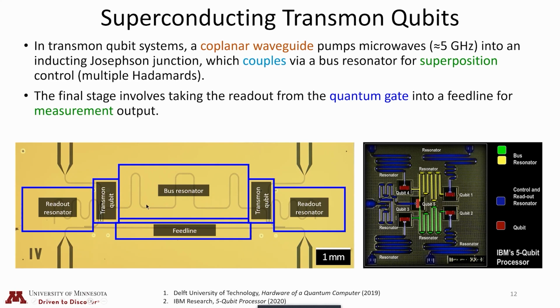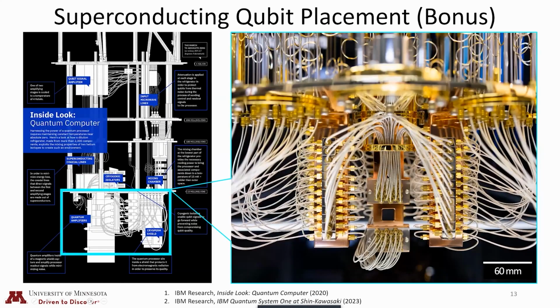You're left with a specific length of wire, but in order to fit it onto a chip, you can squeeze them together like this. But there are some other research efforts where you can turn it into a fractal architecture or fractal design to decrease the area which this line takes up. So all of this can fit into a small space, technically roughly the size of the transmon qubit element itself. And then again, here is an example of where this chip lies.